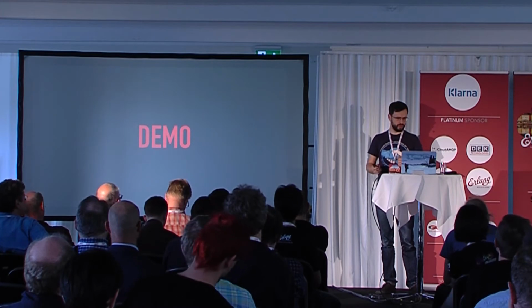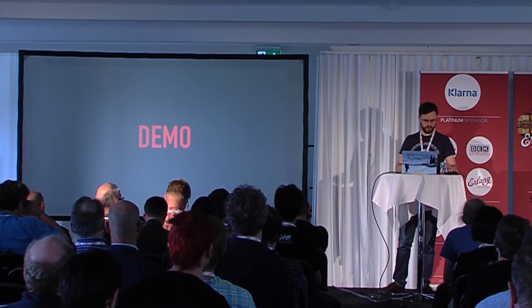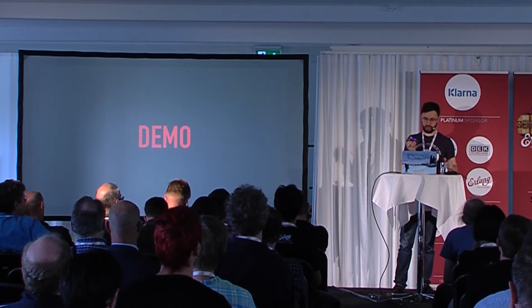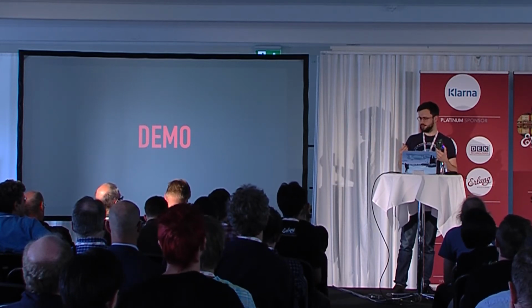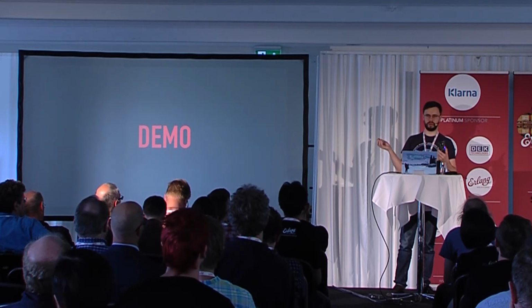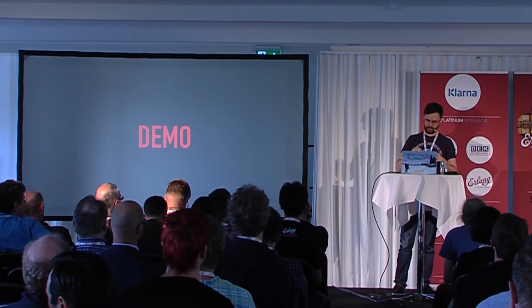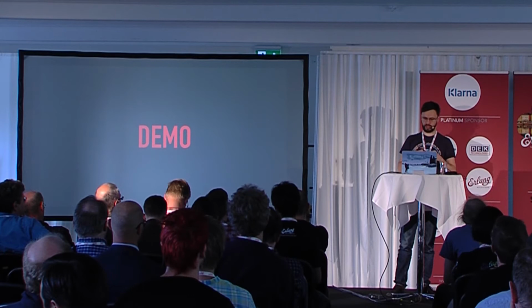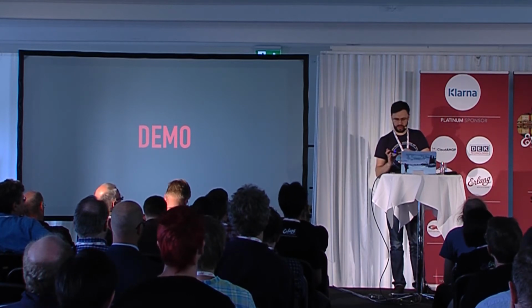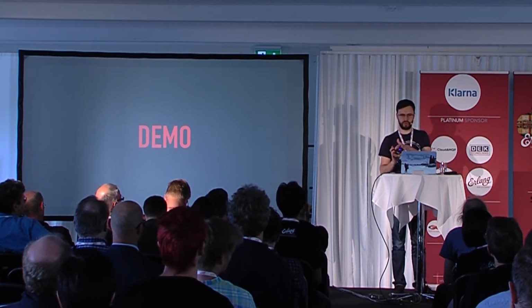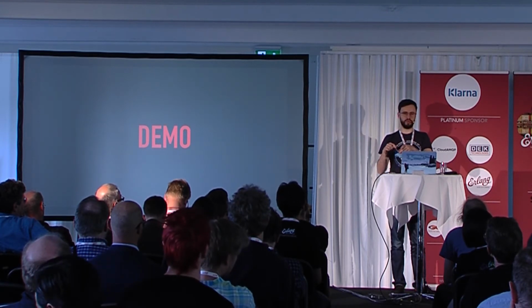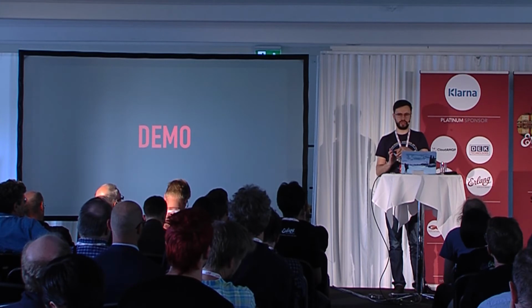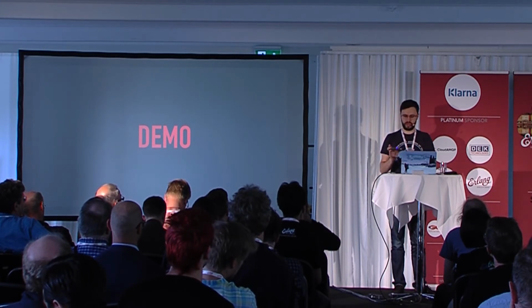So I'm gonna do another demo. I'm gonna use just the board, but I'm gonna connect a PMOD to it. I brought with me the PMOD ACL2, the accelerometer one. And I'm just gonna plug it in. In this case, I don't need to reboot because I didn't talk to this. If you just plug it in, the pins are in some normal power state, so it doesn't mess with anything. So actually, I don't have to reboot.